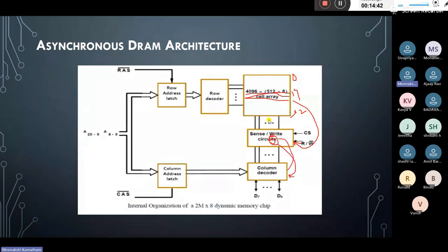So these are the internal things that should occur while selecting the row address and column address. After selection of the row address, we need to select the column address. After selecting the column address, we need to perform either the write operation or the read operation, based on how many clock cycles are required to complete the big amount of data we are calculating using DRAM addressing. So up to this, do you have any doubts?